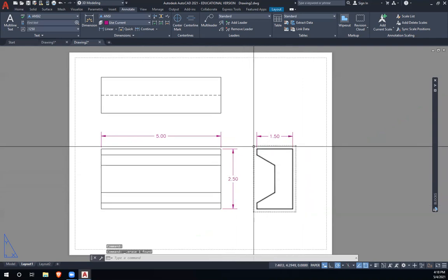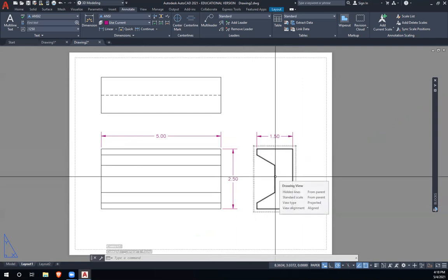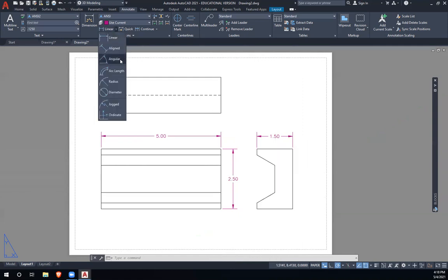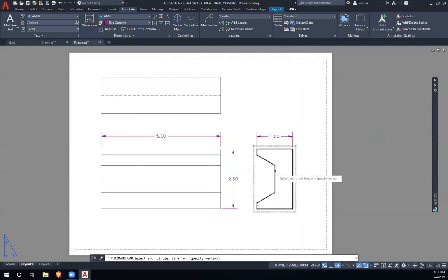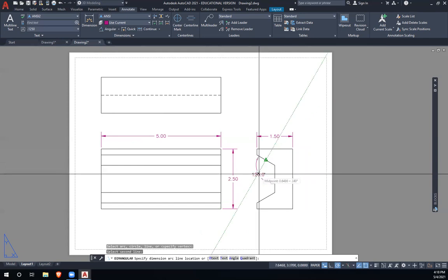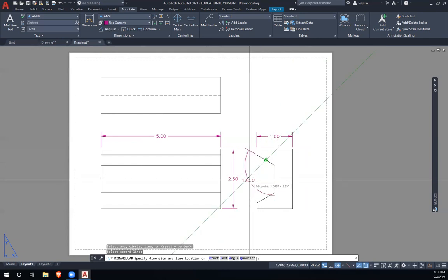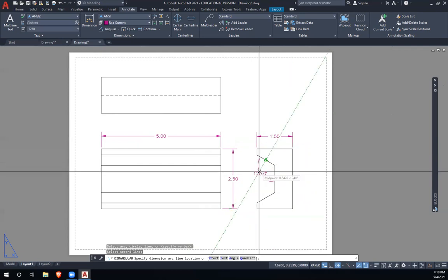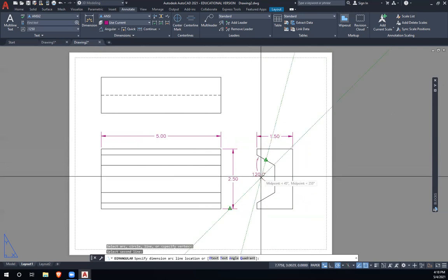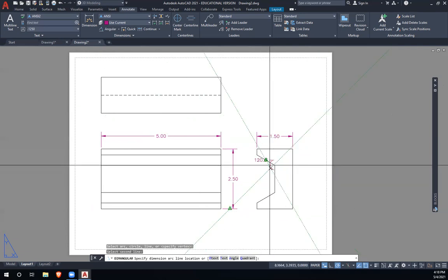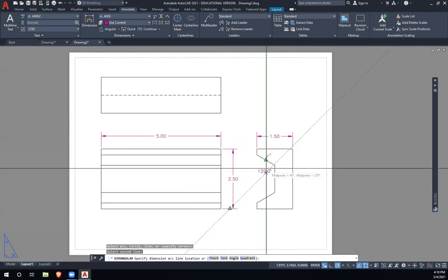Now I might not have enough room, so I have some angles in here to dimension. So let's see if we can get those in there. I could dimension, just click on these 2 and just put a dimension in here, but then I want to put it out here. There's not a great way to do that. And using 120 degrees instead of a 30 degree from the horizontal kind of looks better.